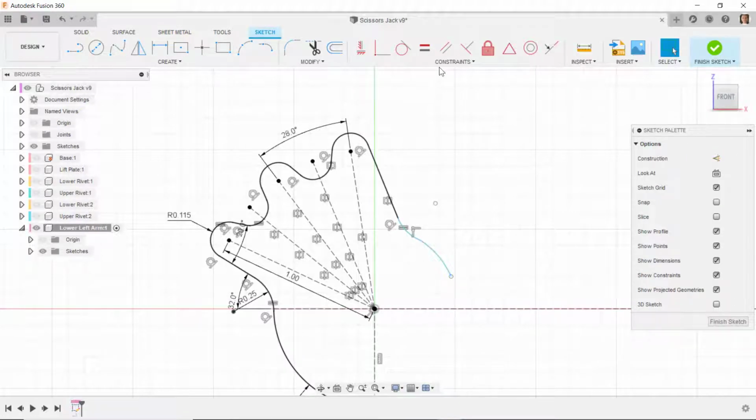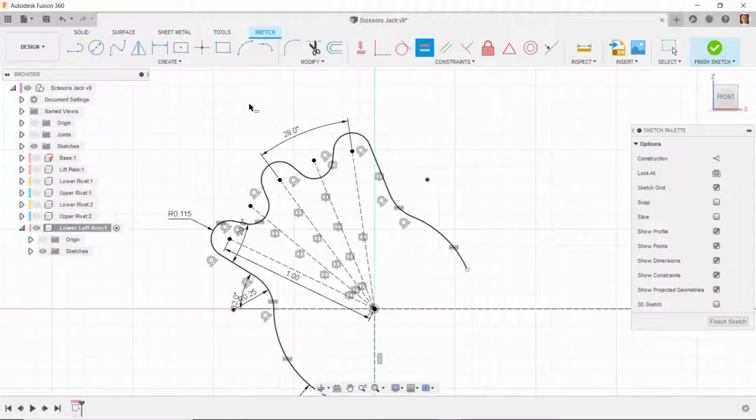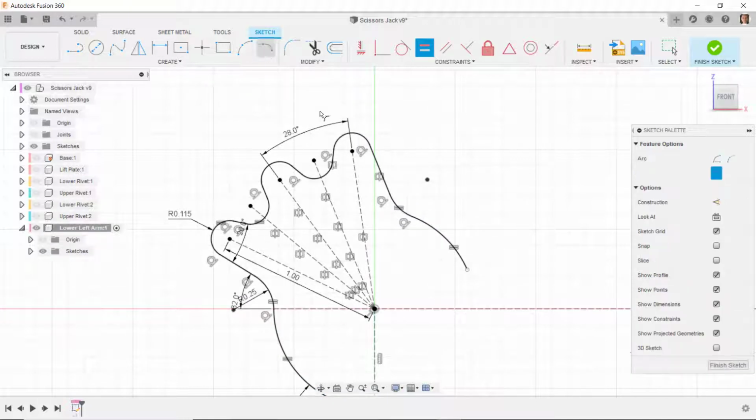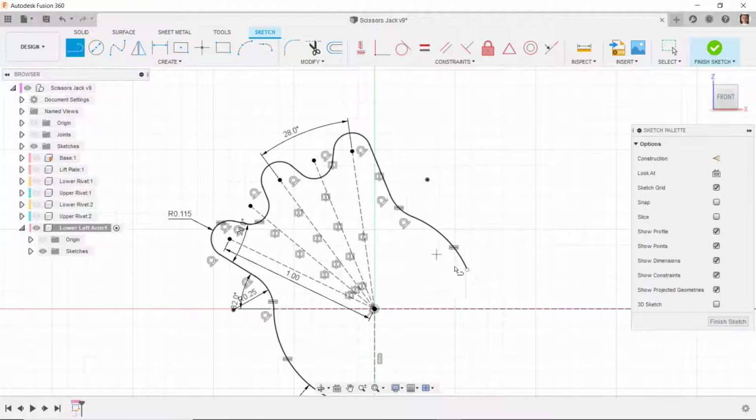I want these 2 arcs to be tangent, so I'll do this arc is tangent to this arc, and I want this arc to be equal radius to this arc. I'll then put a tangent arc here, so I'll do a tangent arc over here. Now we could do this with the line command. If I click and hold, it will come out as an arc, and can then come over here and then come over horizontally and put this horizontal line here.